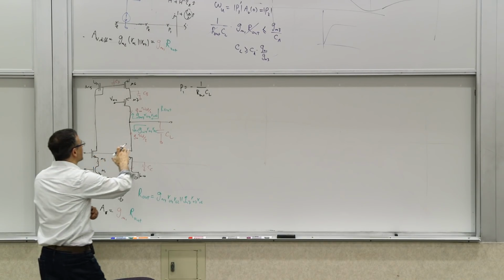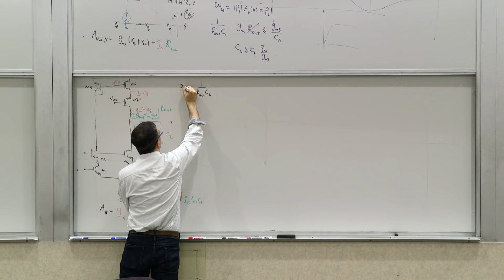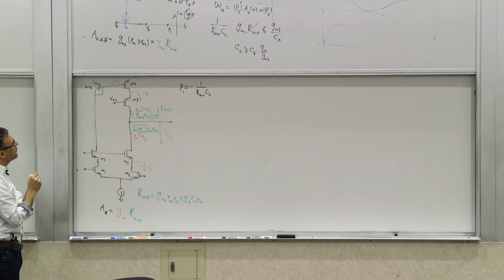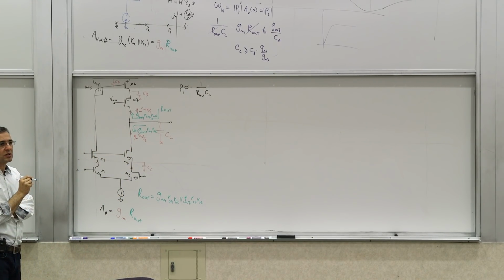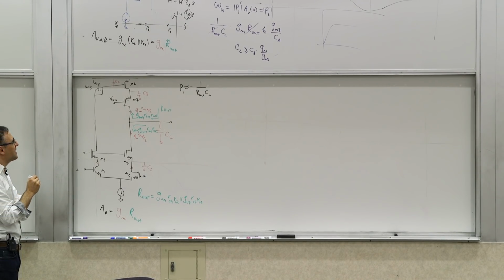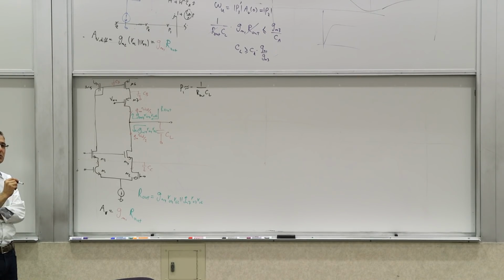So this is not exact anymore, right? I mean, just because of those couplings between the time constants. This is an approximation now. Which one of these 3 would you say shows you the largest time constant? Well, let me ask you this question. Between CA, CB, and CC, which one is the larger capacitor first? CC or CA?